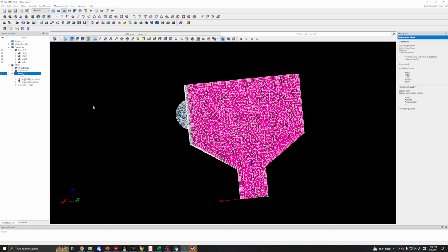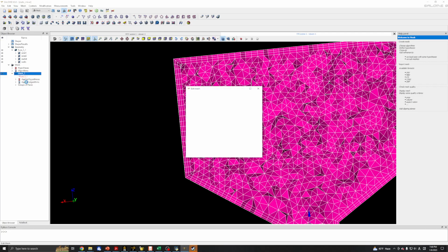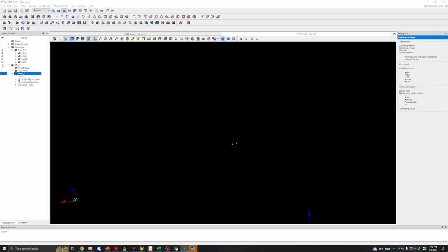try another approach. So the idea is to make the cells closest to the wall, I mean except the boundary layer, small, meanwhile the rest will be made coarse. So I will reset the maximum mesh size to 0.5, probably, which is a bit too coarse. Anyway, this is not for validation, just for starting, so it's okay.